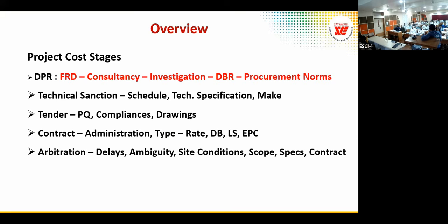Like excavation, we have 20, 30 schedules actually, for excavation alone. For filling, I have 10, 20 schedules. So in the technical sanction, I must freeze which schedule I use for this project. Will I go for 10 meters deep excavation? Will I go for 10 meters high filling? All that has to be defined in the schedule.